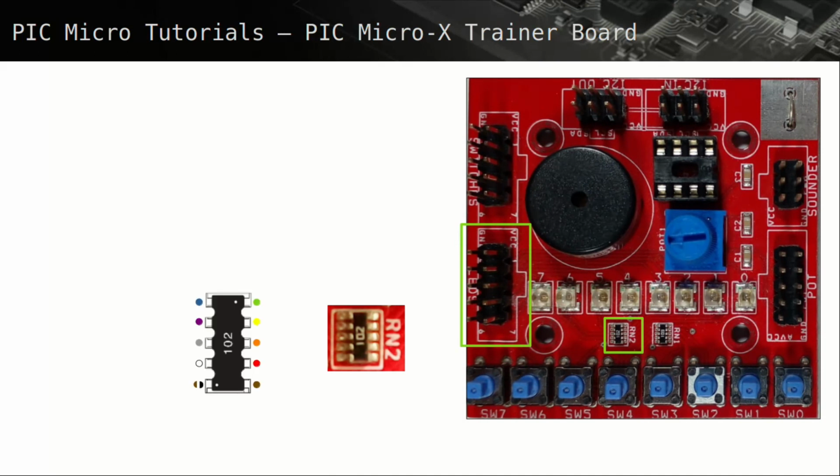Here, the resistor network pin numbers are associated with resistor color codes for easier diagram reading. This resistor network has two commons on pins 5 and 10, and from 1 to 4 and 6 to 9 there are 1000 ohm resistors between the commons.